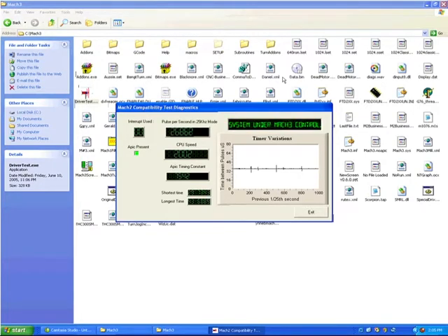Take over in 1 second. Now this is a good waveform for Mach 3. In fact, it's pretty exceptional. At approximately 38 microseconds between interrupts, we have a flat line. These little jittery lines you see are slight variations or microsecond jitter in the pulse stream. This won't affect your motor typically. Those are very small variations, and this waveform is considered a very good one.